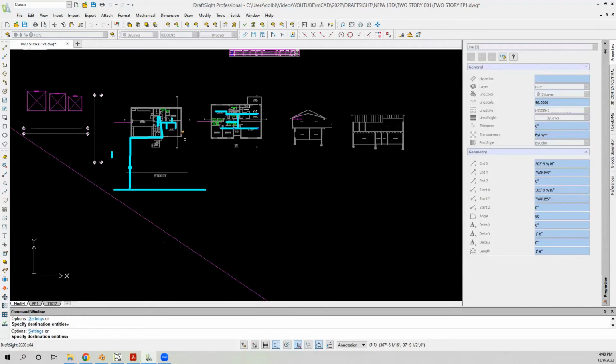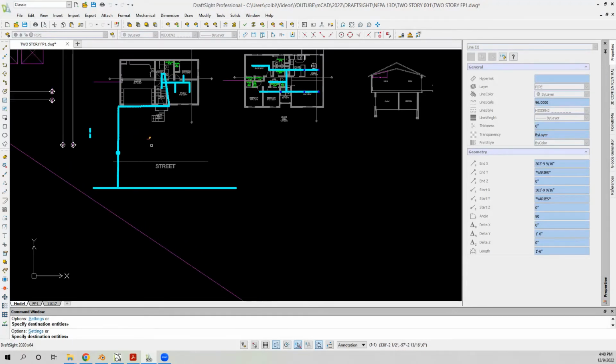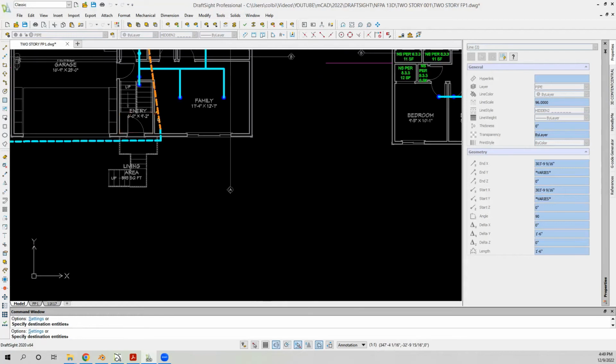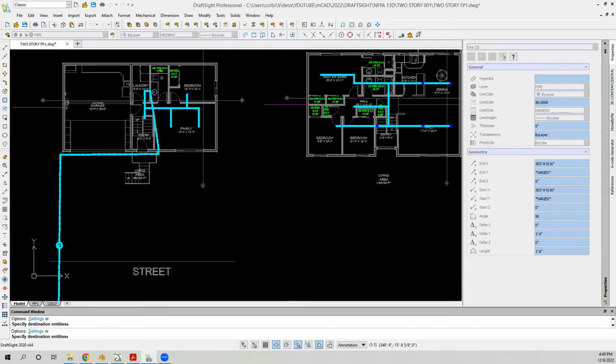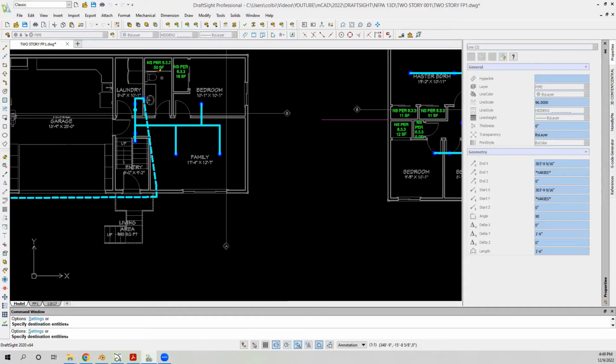You want to make sure, they got NFPA 13D, they got the signs you're supposed to be putting up, letting people know they can't just put a water softener on your line coming in before it breaks off to the sprinkler system, that type of thing. Can't be doing anything to reduce the flow.